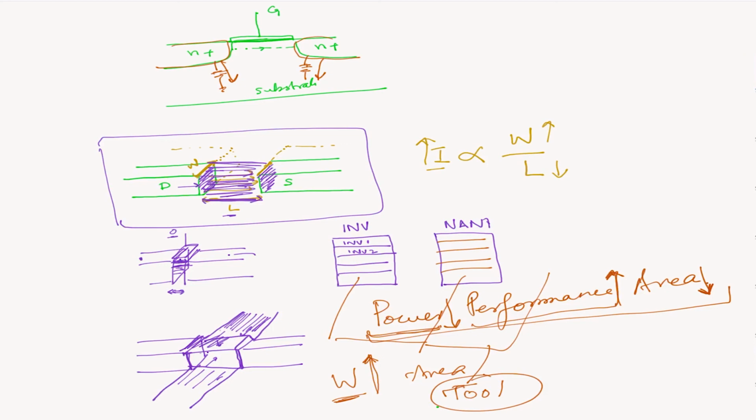Of course, there will be situations where as you increase the area, power goes higher. But the job of the tool is to keep all those factors at an optimum position. And maybe in a given circuit, you are not concerned about the area, but you're more concerned about the performance. And maybe in certain other areas, you don't care too much about the power because you need maximum performance. But if power is the requirement, then you want to make sure you keep the size of the transistors small.